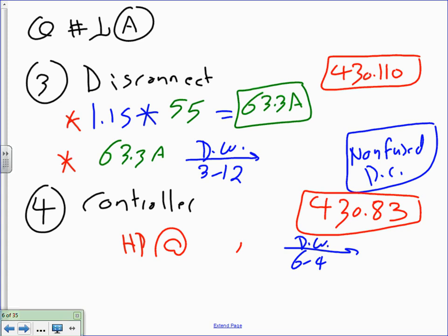And what size disconnect? They go 30, 60. If you go there, 100. If you don't have the table in the test, you can borrow it. All you need is just one page, really. We're going to be using it a lot, so you can borrow that page. Anybody know what the answer is here? 100 amp? We're looking at a 100 amp disconnect. Non-fused. Why non-fused? Did you hear them saying fuse it? This is just a dummy thing to shut down the system safely. That's easy. Any comments, guys? Any questions? Disconnects?